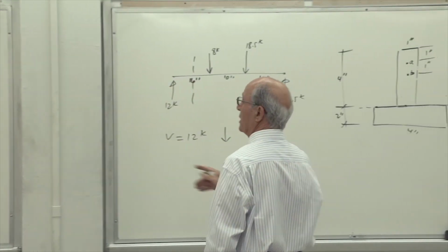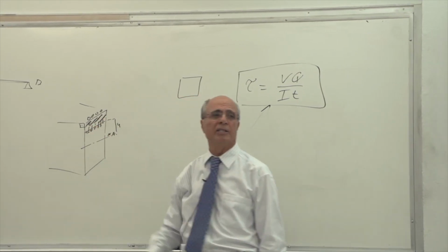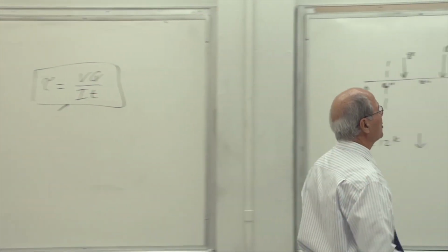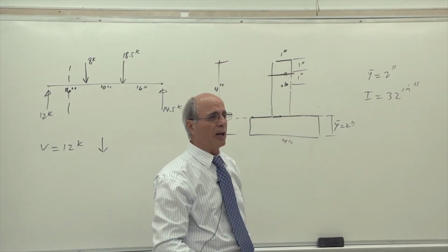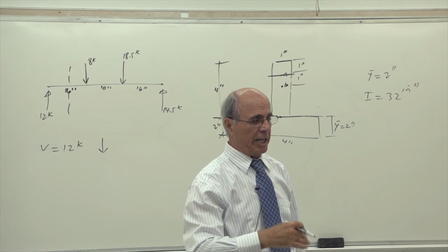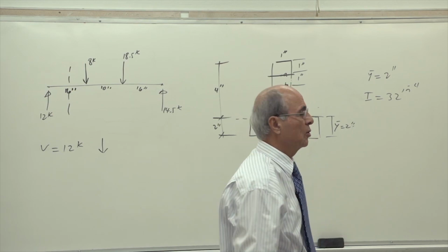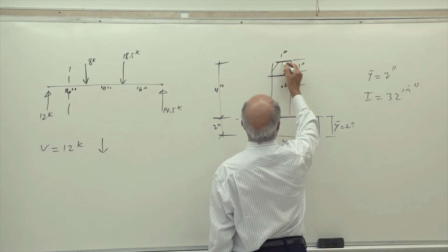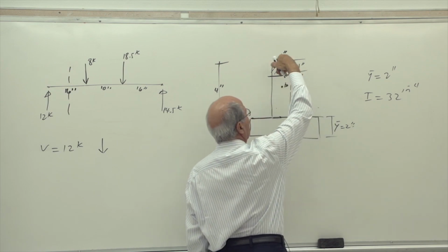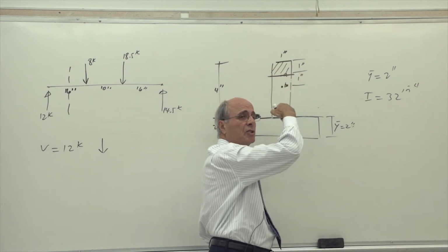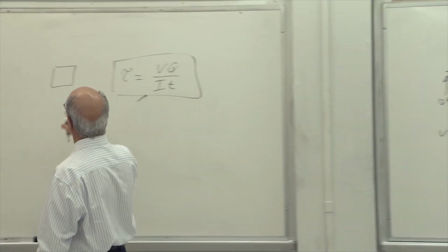So I want to calculate that based on what I did here. What do I need to do? I need to define this line. Is that correct? That line for A is this. So in other words, you make a cut here similar to a cut there. You draw a line there. The area above that is the Q. That little cut will be the T. Is that correct or not? So you are cutting, in a way, this much Q from the rest. You are looking for shear stresses going vertically and shear stresses going horizontally based on your state of stress. I did not finish that one.